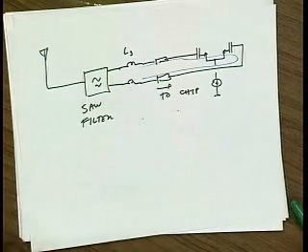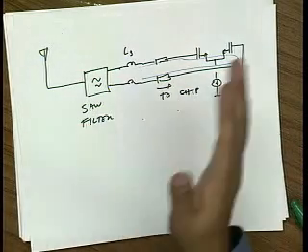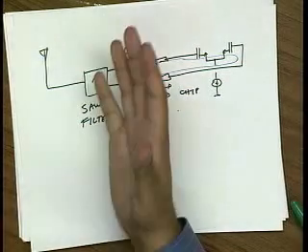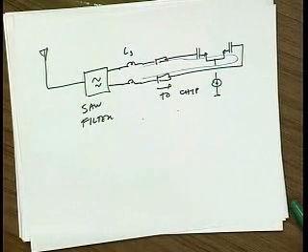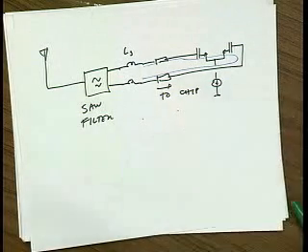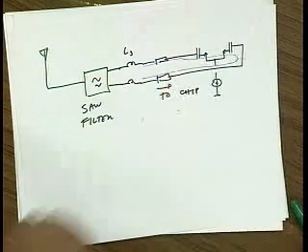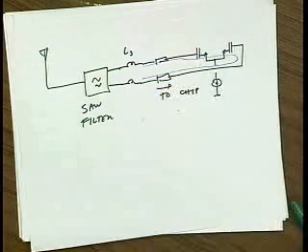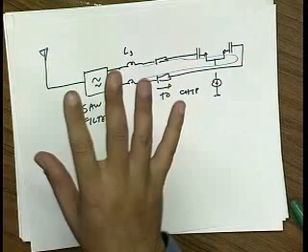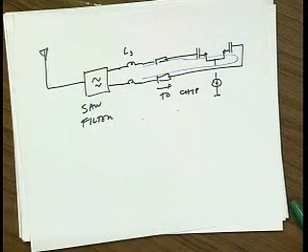Now there's of course other advantages of going differential, which you've learned about in other classes. Differential amplifiers have good power supply rejection. They have good immunity to any common mode signal that's picked up. So any kind of substrate noise that's picked up in common, let's say from a digital stage of your design, will get rejected by the common mode rejection ratio of this amplifier. So going differential has other benefits as well.